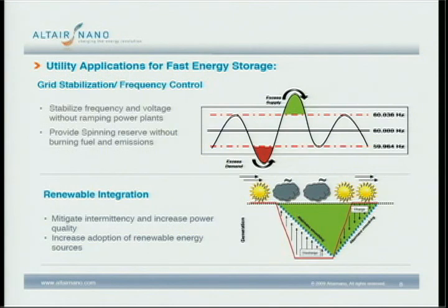We don't have to cover all of this energy. All we're trying to do is cover enough to allow the generators to have an optimal ramp rate, so you're not affecting their post-combustion controls or their efficiency. And on the backside, as the sun comes back out and you have a burst of power, we can absorb enough power to once again maintain a generator's ramp rate. I've got a slide a little later on how this affects how often frequency regulation occurs and how much regulation you need to buy. We'll talk about how that increases based on more of that on the bottom.